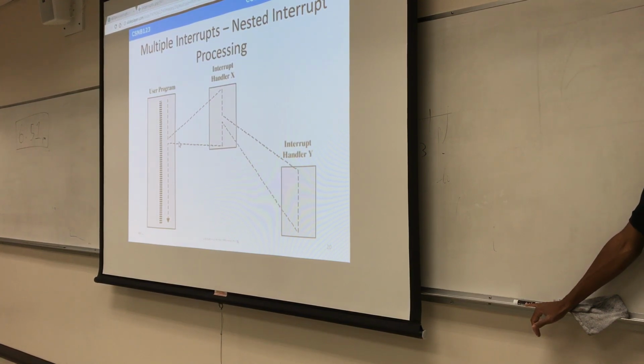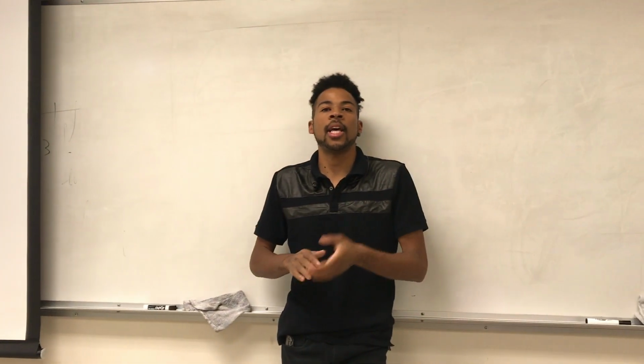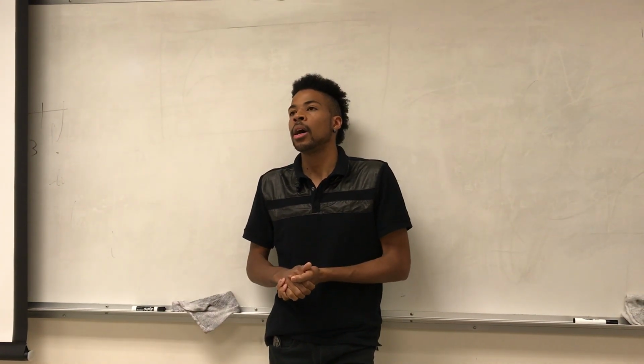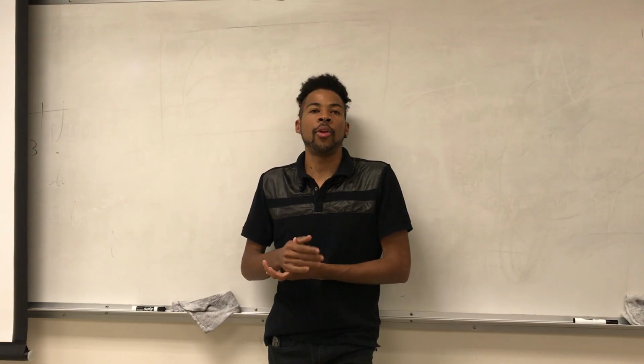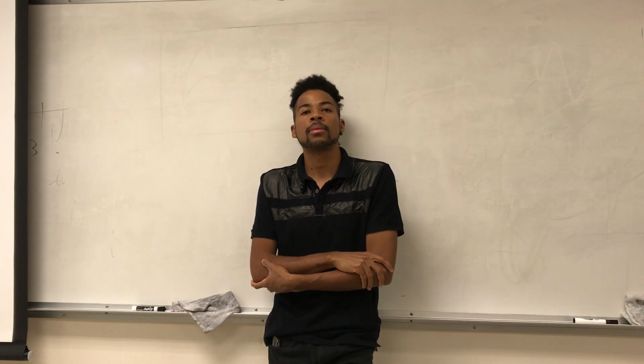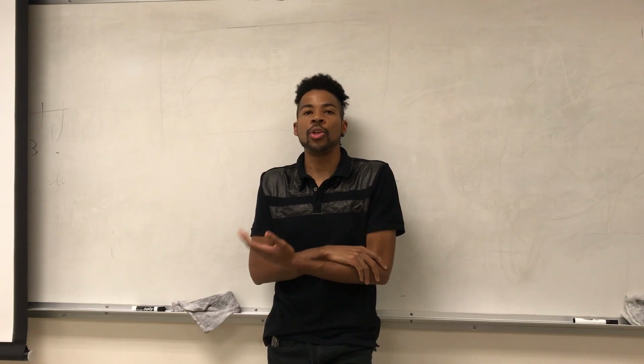True. That is one thing: if you kept the information from each interrupt that occurred, you could have consistent high priority. Actually, it wouldn't even be a problem, since you'd have the queue. So let's assume in this particular case that you not only lack nesting, but you also lack the storing of the interrupt that you held before. So that means you just lose a whole bunch of interrupts. Yes, pretty much. You can end up losing all that information.